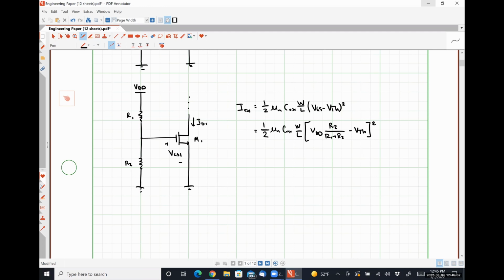So the more you use it, the more the state of charge changes and the more the voltage that's being supplied changes, right? So for a sensitive electronic device, obviously it has to be designed to operate over a range of voltages and a range of temperatures. And to facilitate that, we have to use devices that provide stability, okay?